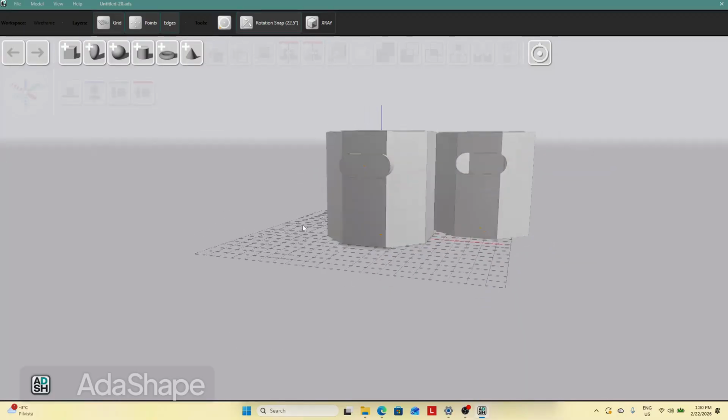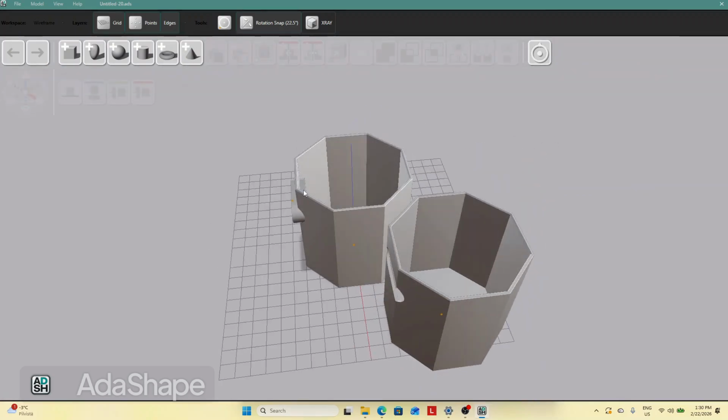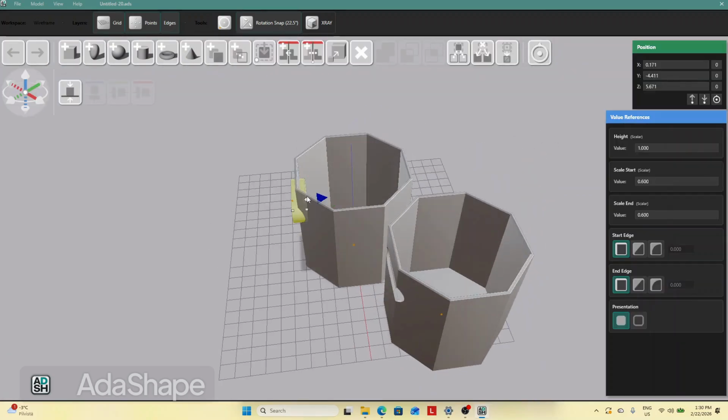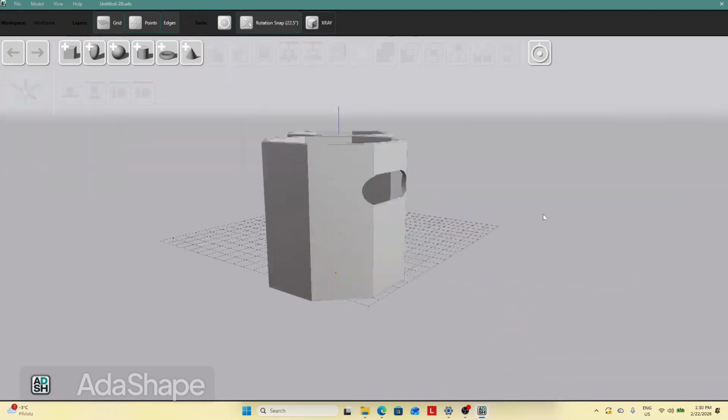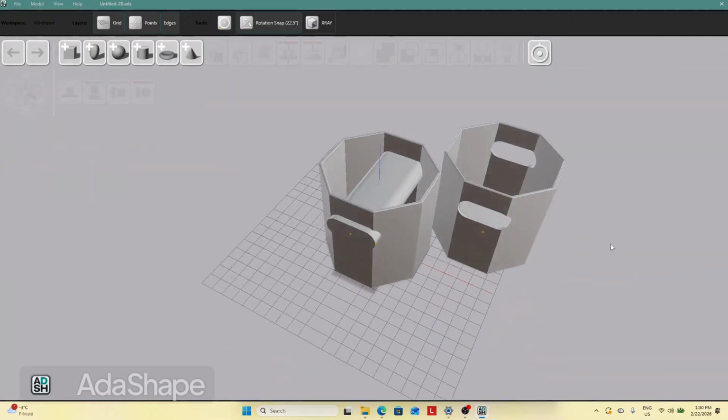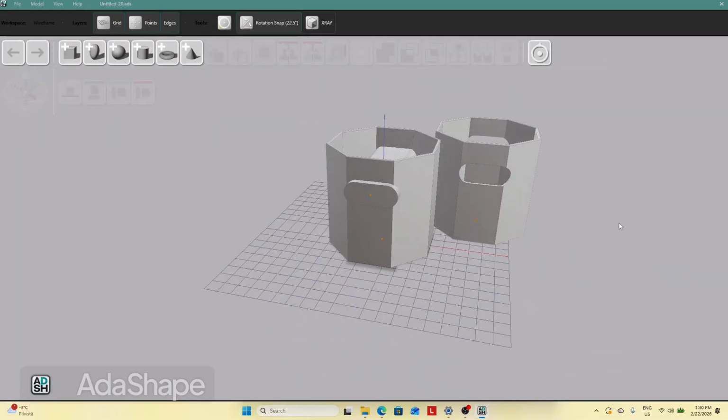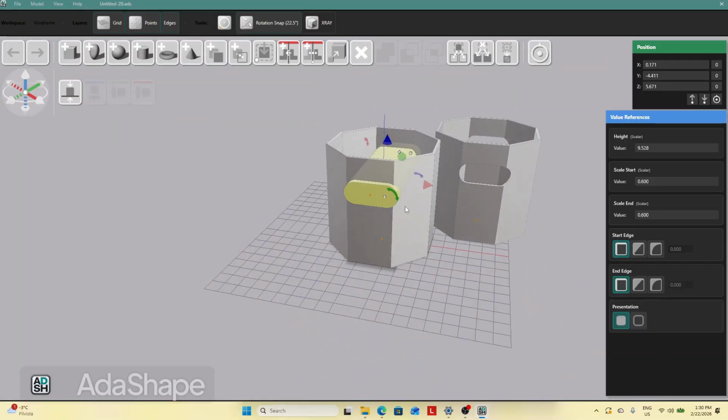And in matter of fact, maybe we want to make it symmetric. So we can just take this part over here, take this distance widget, and then extrude it all the way to the other side. So now we have this nice symmetric hole. Maybe we will make this slightly smaller. I don't like the way it goes over those borders.